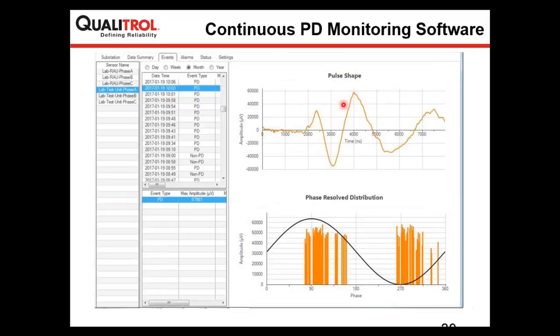For each of the recordings, you can see the detailed categories. The best feature of this software or the monitoring system is that whenever it performs a recording, it categorizes every recording. So here in this recording you have only one type of category. If there is different partial discharge activity or different noise signals, these will be categorized separately.